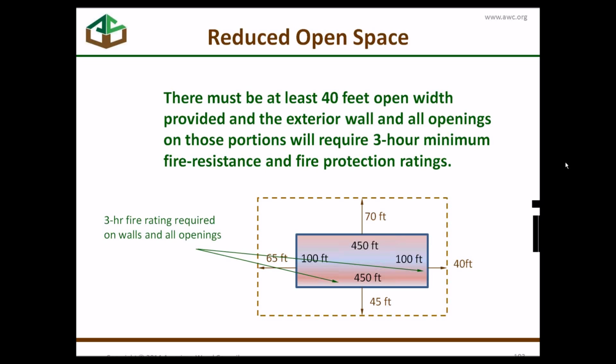But related to the area increase calculation, that W is only a maximum of 30 feet, correct? Correct. Unless you comply with all the provisions for an unlimited area building and all those conditions, sprinklers and so forth. Right. If you don't comply with all those conditions, it stops at 30 feet. That's correct. You can only plug in 30 for your W in your weighted average calculation. Yeah, that's a really good question. Okay, and a really good answer.